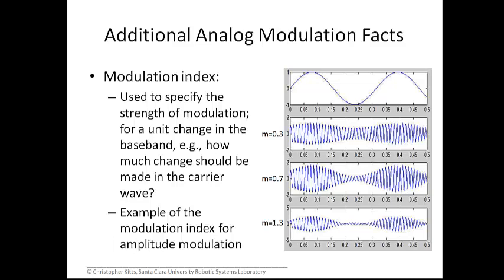And so you can see that that's what's happened actually for our last plot for the modulation index of 1.3. You can see that moving left to right, the amplitude gets bigger and then smaller, and then it gets really, really small, and then slightly bigger again, and then smaller. So that slightly bigger again isn't actually slightly bigger, it's gone negative, and the wave has flipped. And it can be very difficult to figure that out. And so you can be too aggressive, is the point.